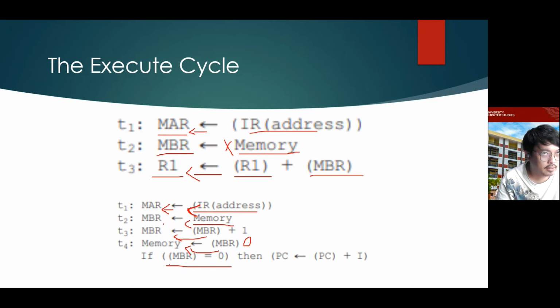Before the next instruction is fetched, the PC will be incremented by 1 if the MBR is 0. Then it will be loaded to the PC.